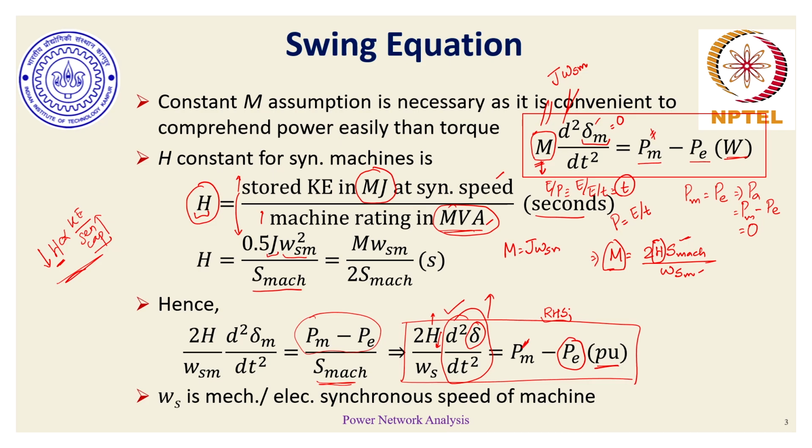So the LHS products would balance out each other, and with a lower value of H in case of high solar PV and energy storage, the corresponding double derivative term will tend to take a higher value, which increases the chance of having more worrisome cases in terms of delta angle having more deviation or lesser deviation compared to a case where the H value is higher, in terms of lower renewable energy integration. So we'll discuss this aspect specifically in the last lecture of this module. So please have patience with that.